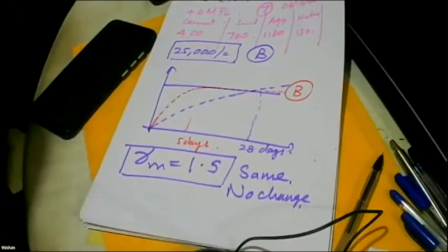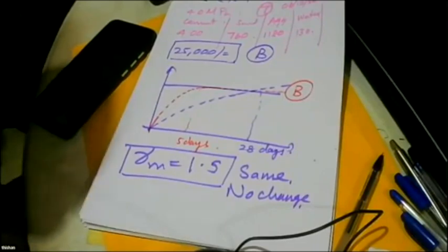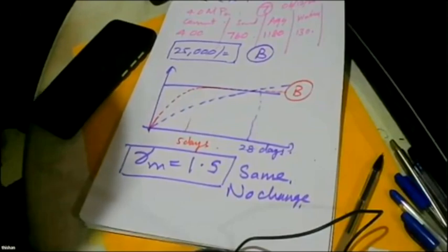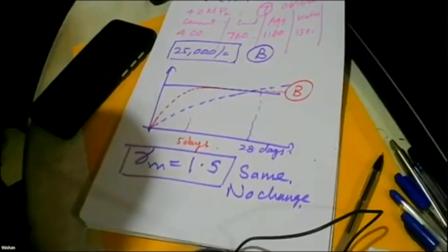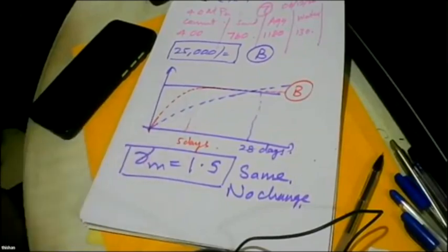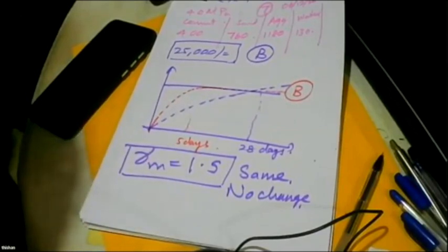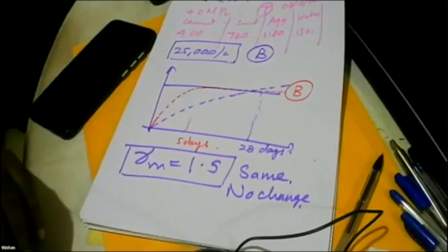And you have to always look for the cost, because we are substituting fly ash for cement, where fly ash costs only 15 rupees, whereas cement costs 40 rupees. And the other important point is, we have to be concerned about the target. So we set a target, 28 days, I like 40. So whether you achieve it in 6 days or 8 days or 10 days or 15 days, it doesn't matter. Then what matters? What matters is, have you cured it?